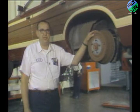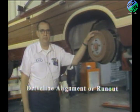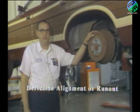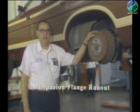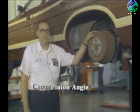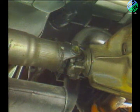As listed in section B and C of the Vehicle Vibration Diagnosis Guide, driveline NVH problems can involve a driveline alignment or runout check, a driveline balance check, measuring companion flange runout, and measuring the pinion angle. Let's review the two most common driveline diagnostic areas. First, let's look at driveline alignment or runout.